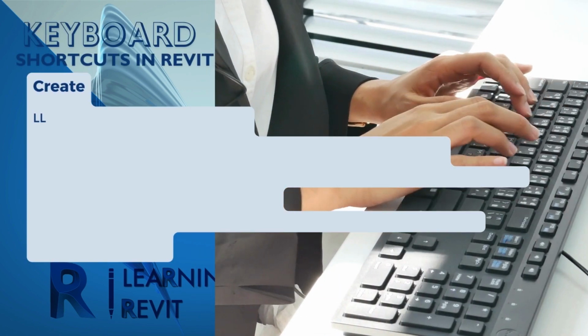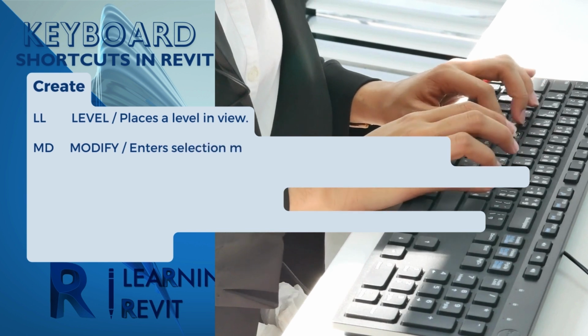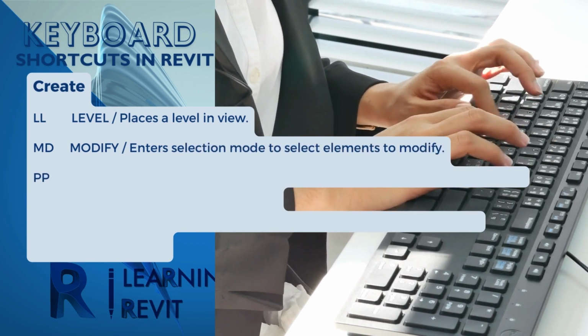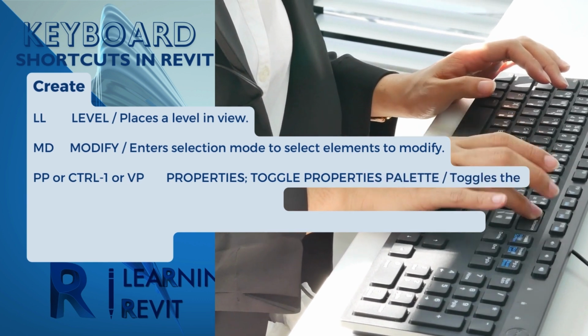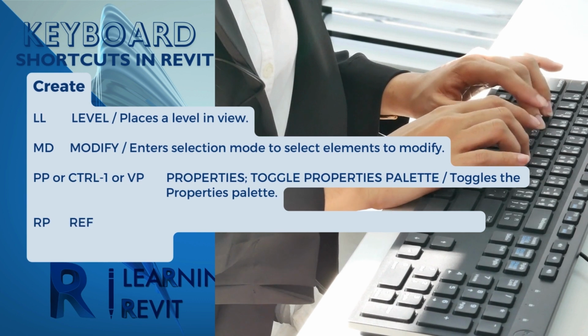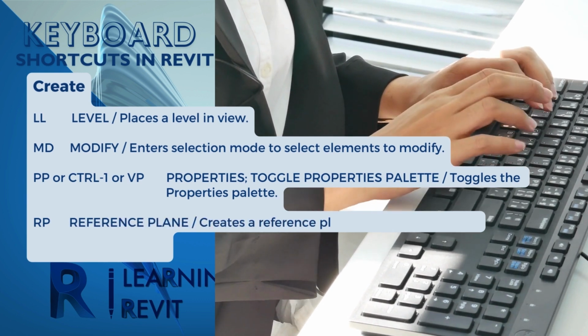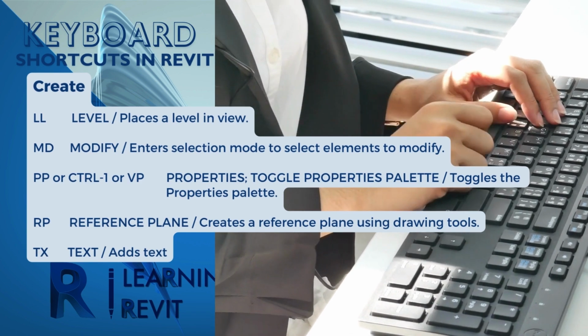LL. Level. Places a level in view. MD. Modify. Enters selection mode to select elements to modify. PP or Control 1 or VP. Properties. Toggle properties palette. RP. Reference plane. Creates a reference plane using drawing tools. TX. Text. Adds text.